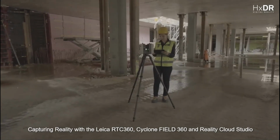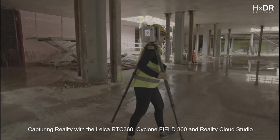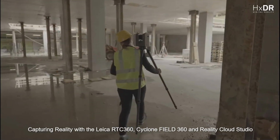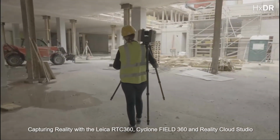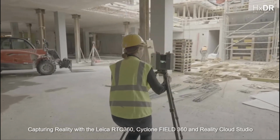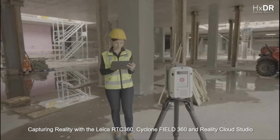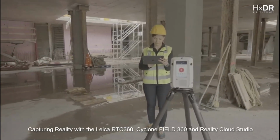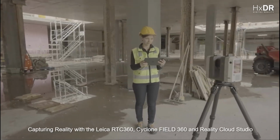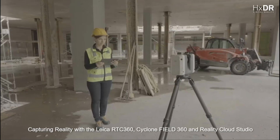So you've got Simona here. She's with Field 360, her RTC. She's collecting scan data, walking around the scene, and basically building up the registration in real time through the tablet. Now, we've added some really cool functionality to Field 360 as well, so you can now georeference directly in the field. But by working in this way, what it allows you to do is create a registered bundle on Field 360, and if you want to, you can send that data straight from the tablet to Reality Cloud Studio.